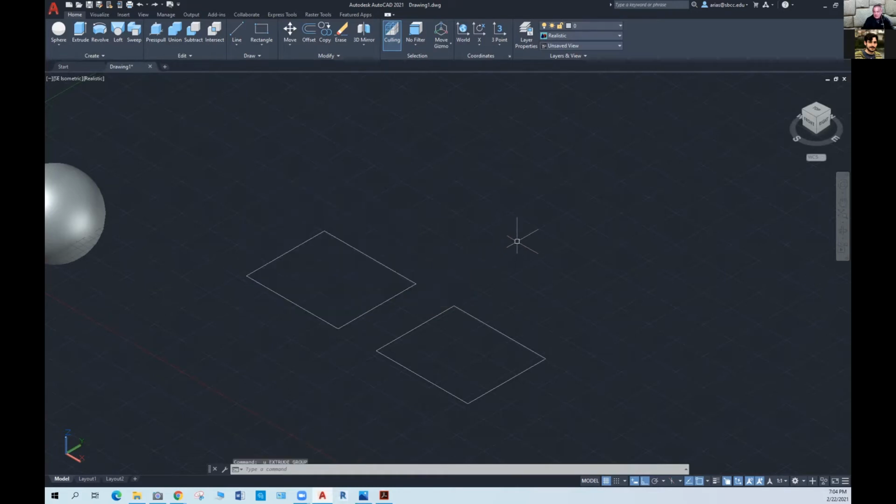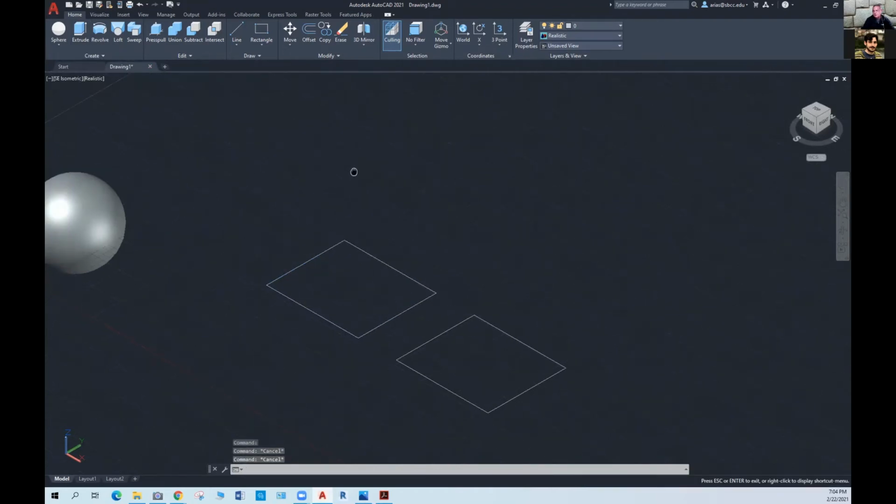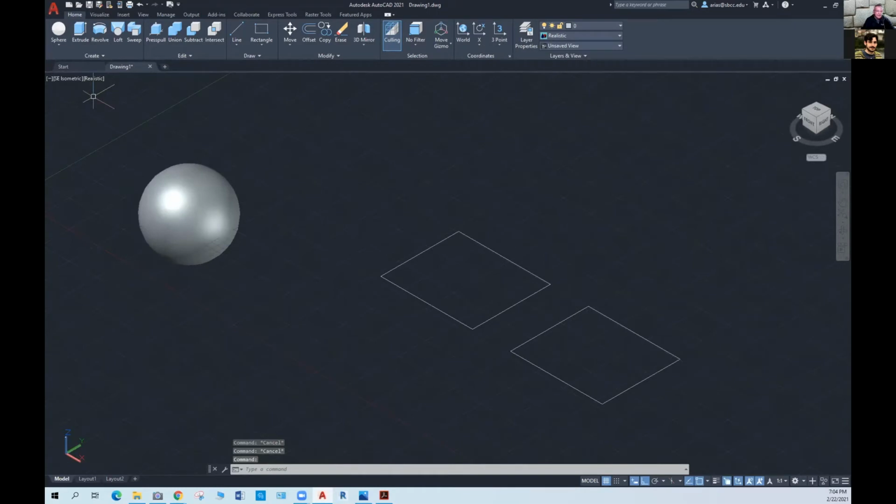It was originally a 2D profile, but I selected it and then added the value on the z-axis with the extrusion, right? So that's another way of creating the geometry in AutoCAD. So once again, I could create geometry by selecting a primitive, or I can create geometry by using a 2D profile and then selecting one of these tools to modify.